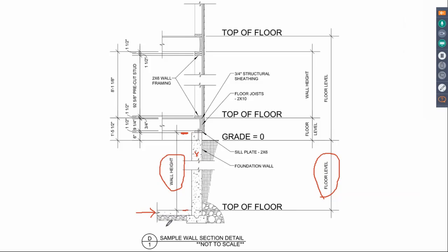So this is a very important distinction, because in Envisioneer, when there is no floor slab on the foundation level, this top of floor reference line right here is going to drop down to the top of the footing. So obviously that's going to accordingly change the references for the floor level and for the wall height. So I just wanted to take a minute to point that out so you'll understand the changes that I'm going to make when I go into my building locations dialog.